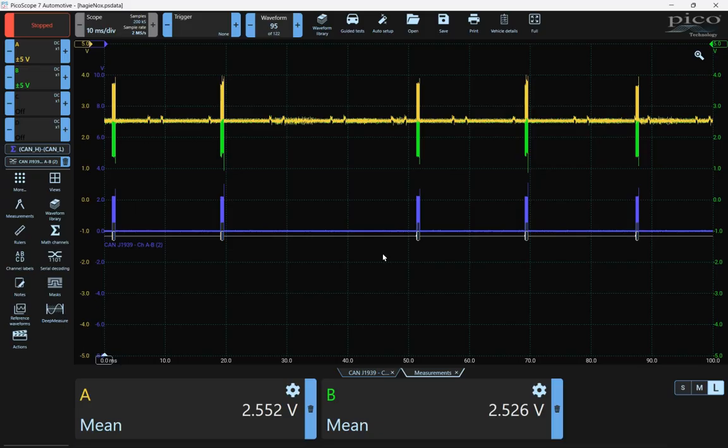There could be a lot more components on this aftertreatment bus, but there's not. In this case, the components themselves were 250K components, and the machine is 500K. Why don't they just put it on the machine bus? Because you would have to change the components so they're 500K. That would add expense to those. That's some of the reason. The other part of it is it does minimize how much we put on the other bus, but this isn't that much data. Probably more than anything, it's the 250K piece of it. So we'll go ahead and go through some of these waveforms.